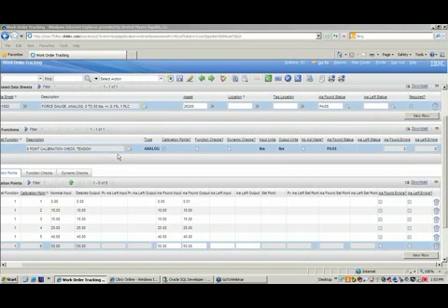The other common thing is, for your as found status for the data sheet and your as left status, you could create escalations in Maximo based on criteria. So if your as left status is a fail, you could have an email notification go out, or you could have a follow-up work order created through an escalation, or maybe even a more advanced workflow process as well. Those are all using the typical capabilities within Maximo, but that's just some examples of how you can use it here.